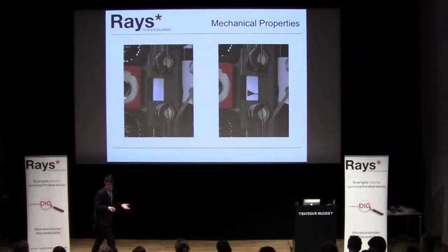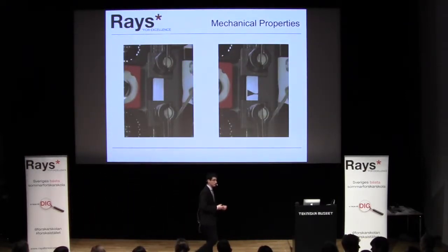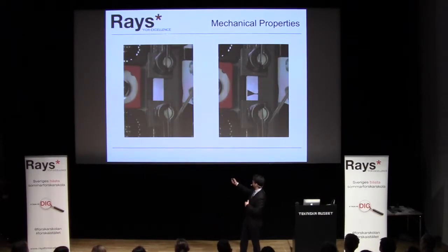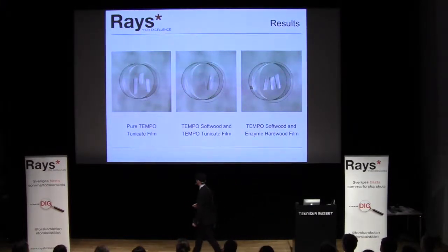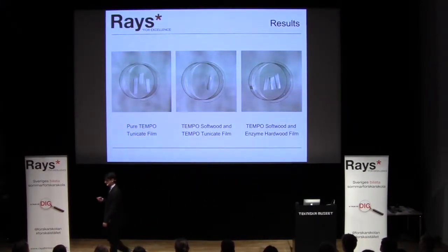Now I'm going to talk about measuring mechanical properties, and we do this by stretching the film. As you can see in the image right here, to your left, the film is currently being stretched. While here, to your right, the film is stretched and has reached something called a breaking point and thus is broken. What we're measuring specifically is the percent increase of the film from its initial length. This will allow us to determine how durable, flexible, and strong the film is. During my investigation, I produced 3 different types of films using the 3D printer.